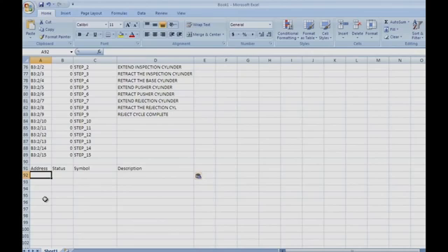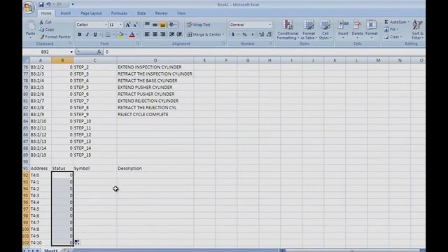So I'm going to start with T4:0 because we know that T is the timer file, 4 is the number that's associated with it, and the first timer file that's available is T4:0. So I'm just going to go ahead and grab that and autofill down to about 10 timers. And again, the status here is 0. And we're going to autofill this as well.